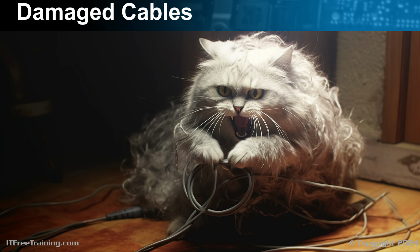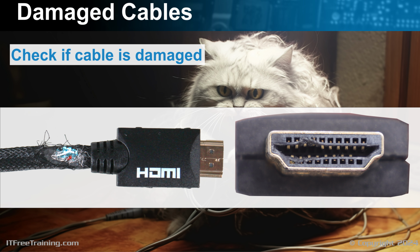If you're not getting a video signal or an intermittent connection or distortion, it's possible that you're dealing with a damaged cable. Modern cables often use blade-style connectors, which offer improved durability over older pin-style versions. Despite their enhanced robustness, blade connectors are not impervious to damage. Consequently, it's wise to conduct a detailed inspection to verify that your connectors remain in optimal condition.